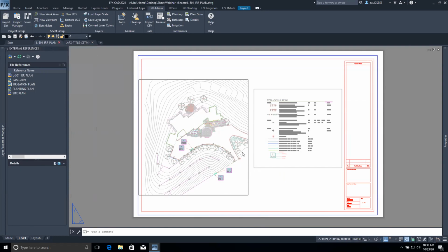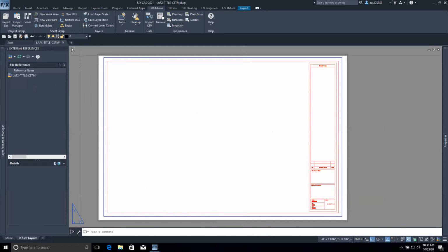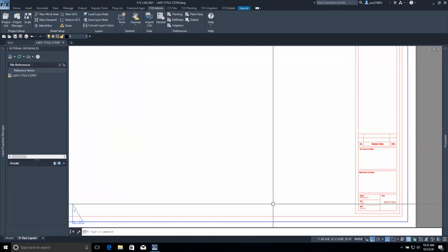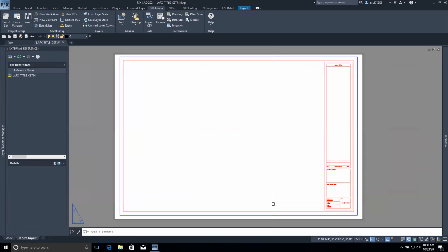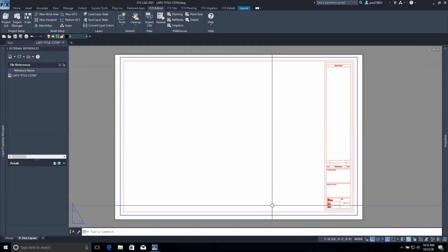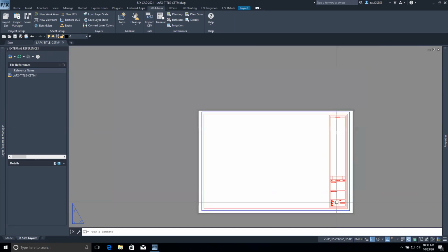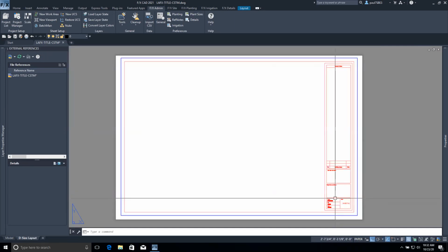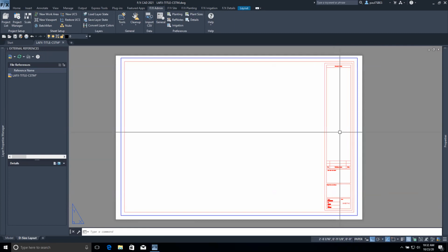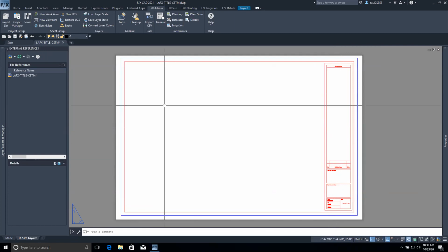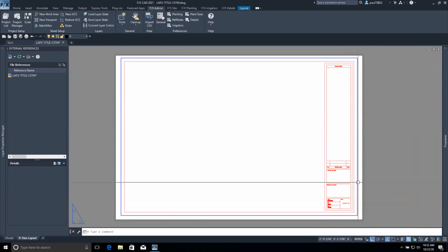So I'm going to close this. And let's set this up as an xref. So in preparing for this, I didn't find a way to carry these text attributes through an xref. So instead, what I'm going to do is save all of the CAD line work and such, stuff that's going to be basically used on all of my sheets.